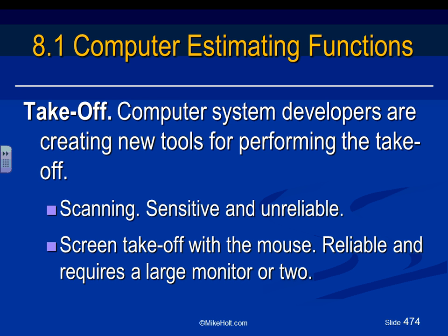They can literally count all these components and take the measurements for your feeders and immediately input it into the software. The problem with this one, guys, is coordination between the engineering firm and the electrical contractor, and sharing material and sharing the same symbols. The other one is takeoff on the screen. Sometimes they scan a PDF file, guys. You scan it as a PDF file. It's identified on the screen, and they do on-screen takeoff, where you can count all your receptacles and your equipment. So these are the on-screen and AutoCAD interface takeoff.